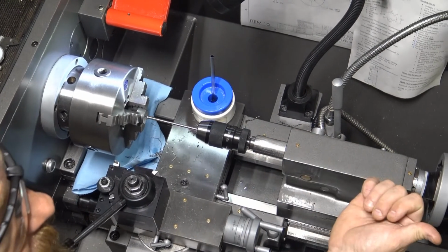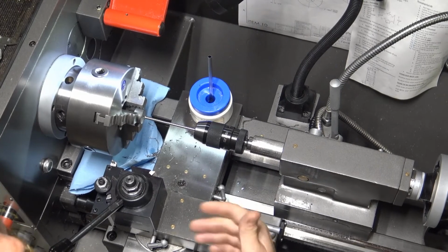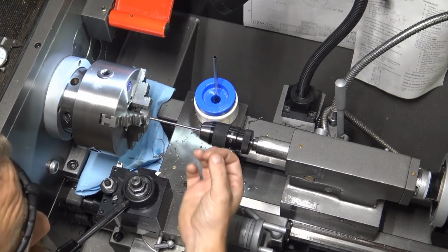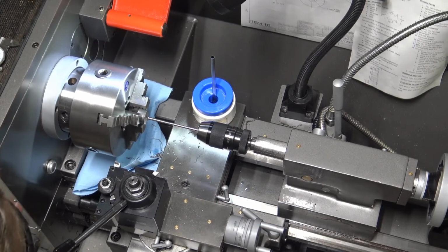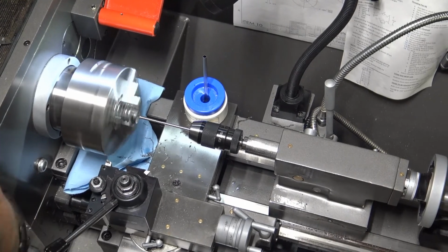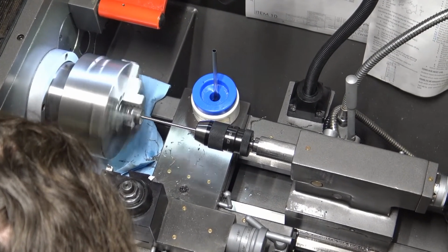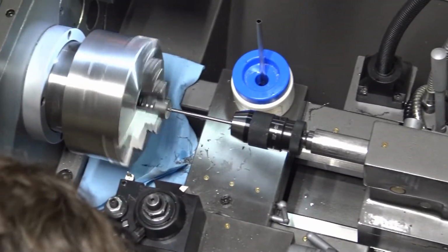When I retract out, or when I pull my tool out, I want to go a little bit quick. I don't want to stay in that hole and just dance around, because then that reamer will start bouncing around that hole and actually making it larger than what we want. So nice and smooth in, let it cut.